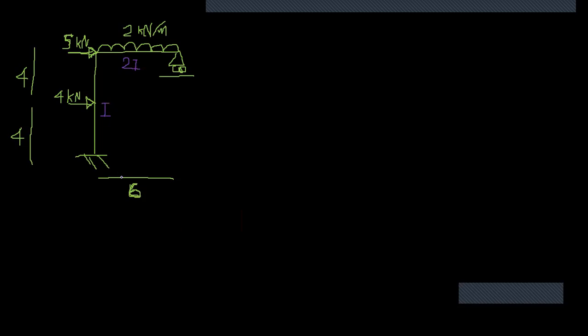Okay. So there are several factors. It is allowed to move, right? Why? Here the horizontal degree of freedom is not restrained. It cannot move in this way. It can move in this way, right? And there is asymmetric loading, as well as the geometry is also asymmetric, right?